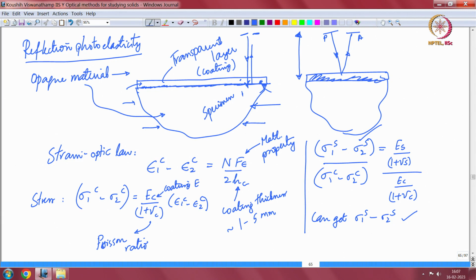We started off by looking at some of the properties of transmitted light, why it bends, why it refracts, why you have birefringence and so on, and then I also introduced this idea of stress induced birefringence, where the presence of a stress field can actually change the refractive index in two directions due to the stress optic law, and then from there we slowly built up these little units which allowed us to interpret the effects of things like polarizers and analyzers and quarter wave plates and things like that, and then this Jones algebra allowed us to put all of them together in the form of rotation matrices and evaluate the net retardation as the light comes out from the analyzer sheet, right.